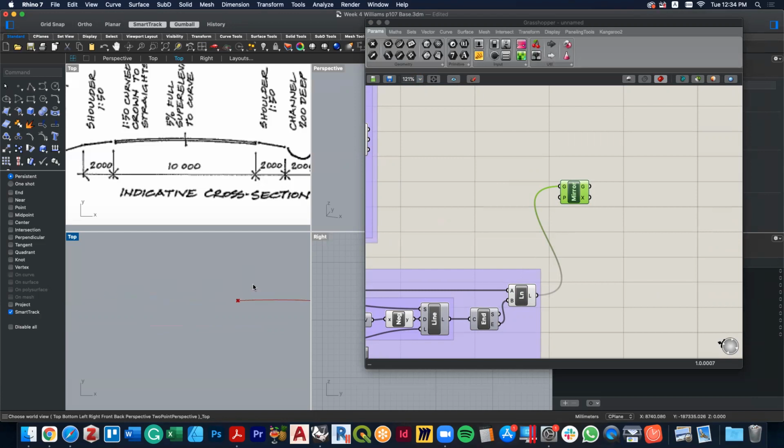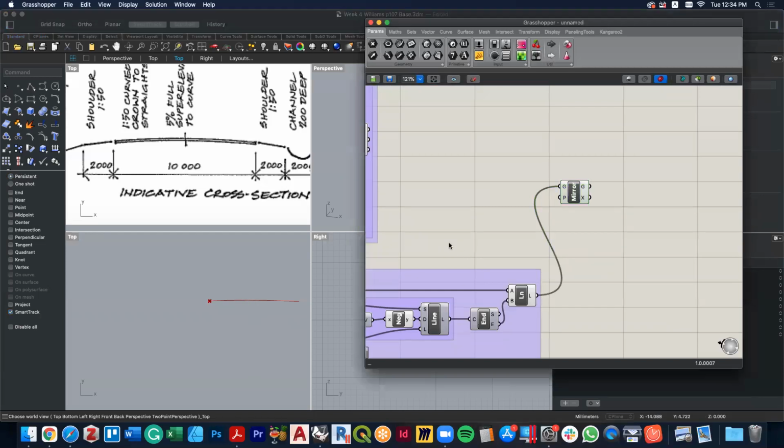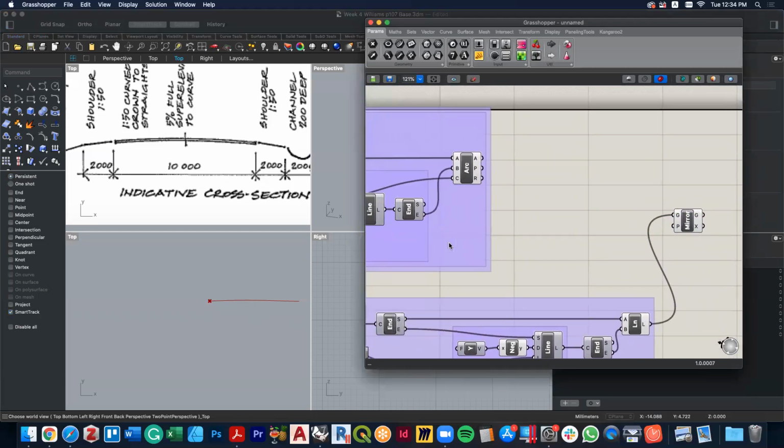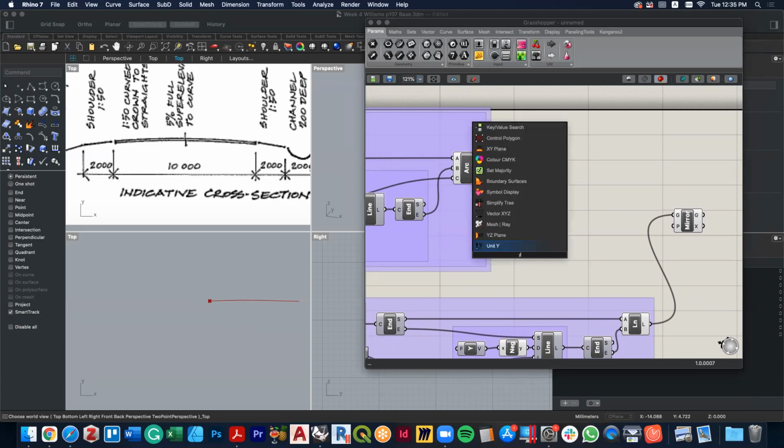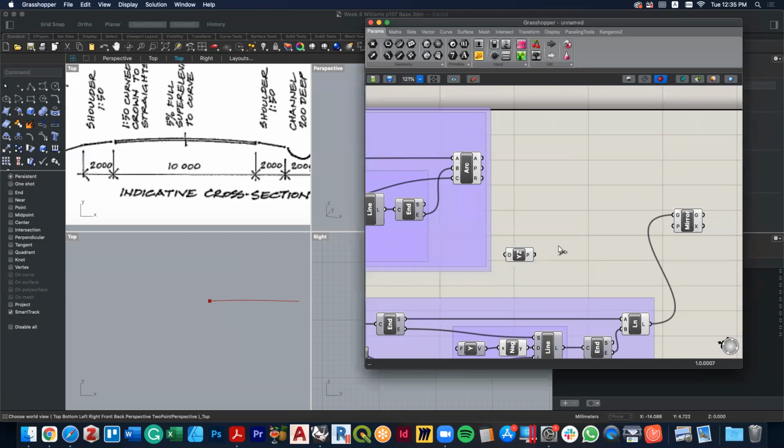Now, if we think about it, the mirror plane is actually based on the center point there, because this road has a center point. I found this out through trial and error, but it makes sense when you think about it. We're talking about a mirror plane because otherwise we're mirroring in 3D. How are we doing that? And so the mirror line, if we look at this axis, is actually going to be along the center, so it's Y. But in actual fact, to get a plane to go straight up to us, Z is in that plane. So if I go Y and Z, then I've got that plane there that I'm mirroring in.